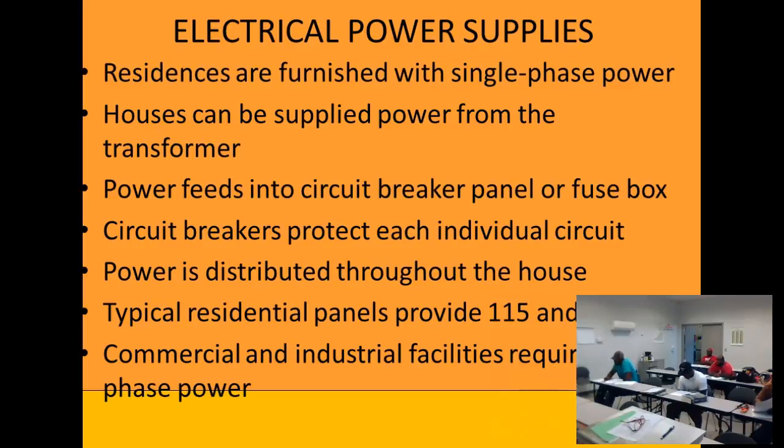And what we had was, I think, E, which means voltage, is equal to I times R. And then on the power formula, P, which is watts for power, equals I times E. So E is voltage, I is amps, R is resistance, P is watts, right? So we have a relationship right here.